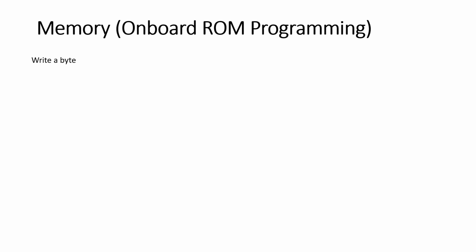But nevertheless, to write a byte to the ROM chip, there is no additional hardware required, but only a certain procedure that needs to be followed. That means what I do is, I start and verify if the new value is identical to the old value, and if so, then I don't do anything, I just skip the value and keep it as it is.